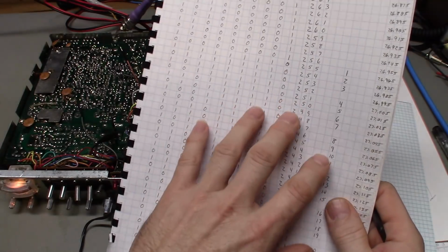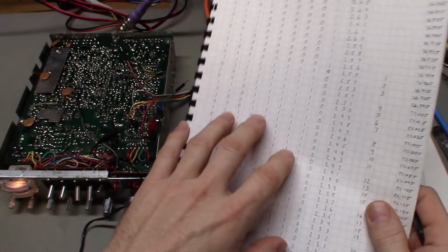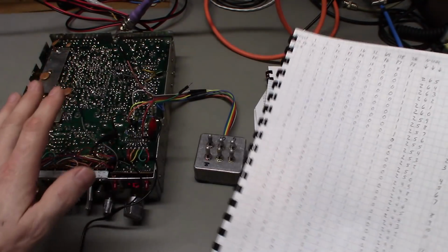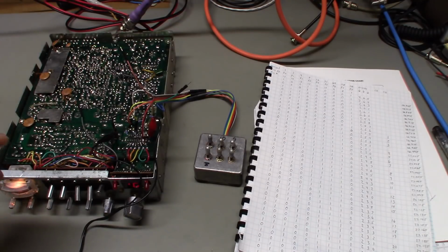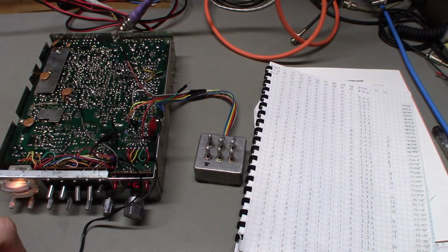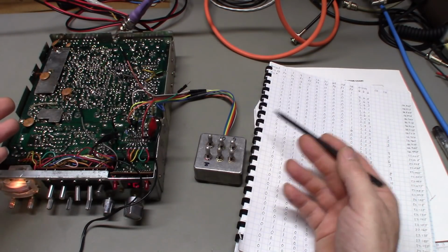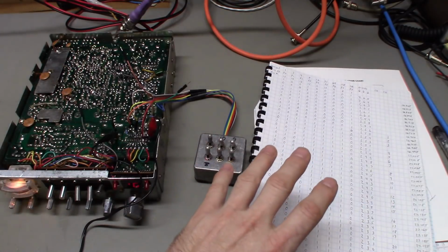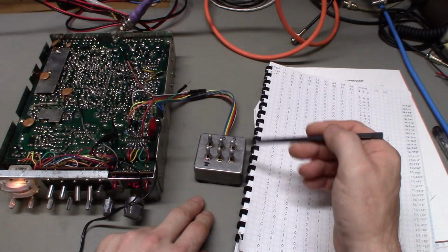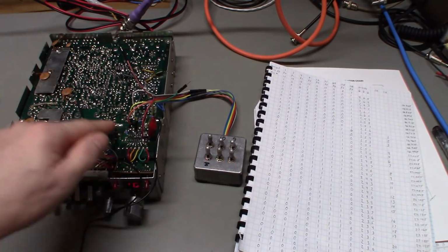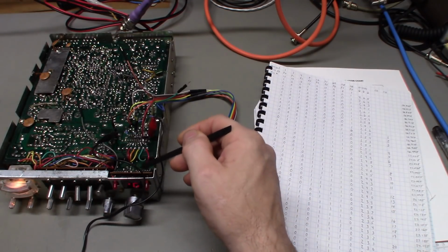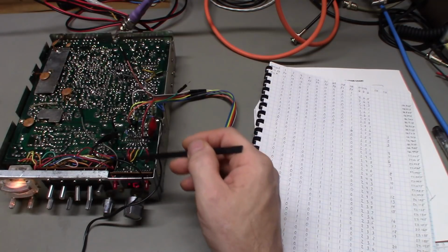But yeah, I'm kind of glad I picked this because it does point out, this is one of the PLL02As, one of the most popular PLL chips ever used. There's millions of them out there. So that's one thing you need to be aware of, some of them count up, some of them count down. I showed the easy way to do it with toggle switches. If you do a channel modification, don't just go attaching a switch that has voltage on one side, ground on the other, and send that straight to the PLL pin. Because when you turn the channel selector switch, you have to remember, the channel selector switch is also providing either a voltage or a ground to that pin.